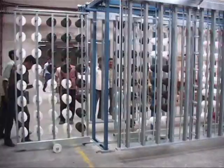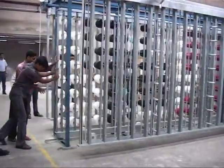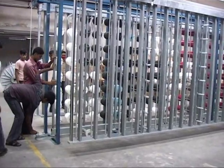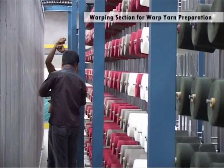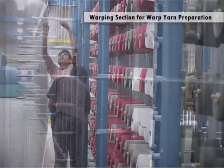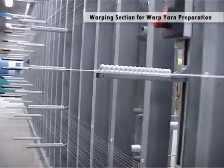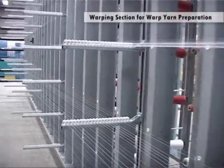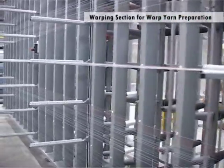First phase, unwinding of the threads from the bobbins and winding on intermediate carriers till attainment of the required total number of warp threads. Second phase, simultaneous rewinding of all these threads and subsequent winding on the weaver's beam. The contemporaneity of these two operations is the prerequisite to produce a beam where all threads show same tension and length.